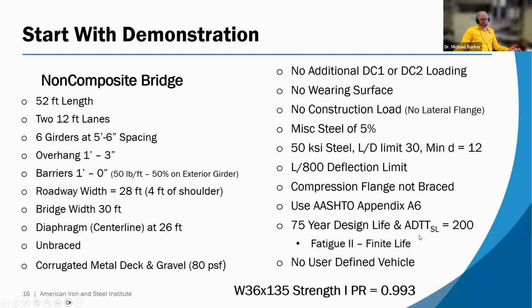I do have an average daily truck traffic in a single lane of 200. That tells us what our fatigue requirements are. And I don't have any user-defined vehicles. We're just using the AASHTO HL93 loading.